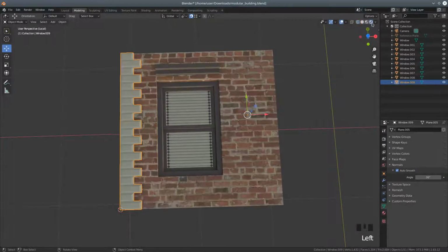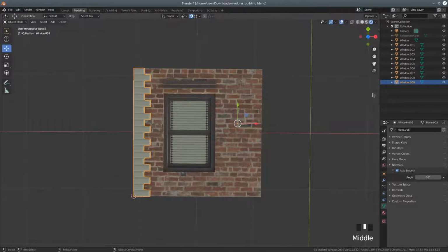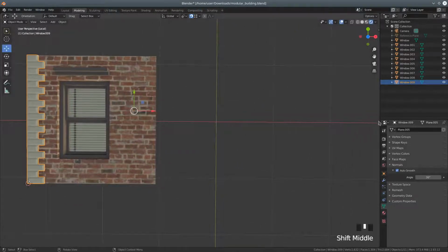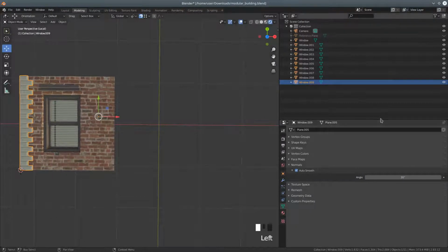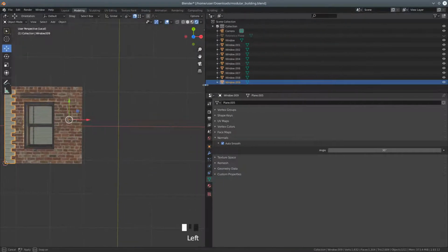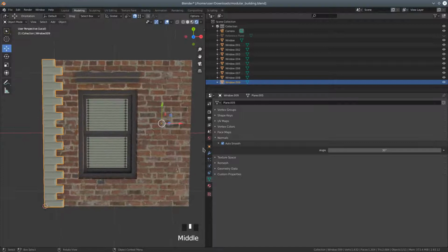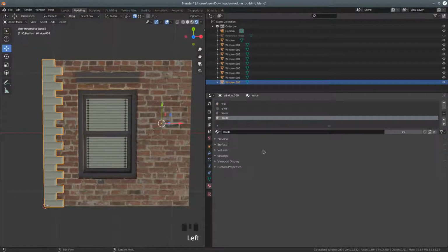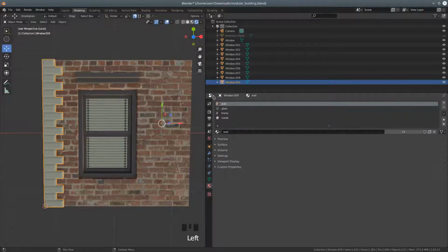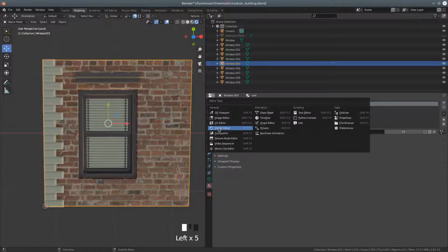We might well have a look at texturing it. So I'm just going to pull out my side window here so you can see what I'm doing. Now what we can do is go to our texture material, and what we want to do is go to the wall texture. Let's go onto the shader editor. Let's select that one. We'll change to the shader editor.